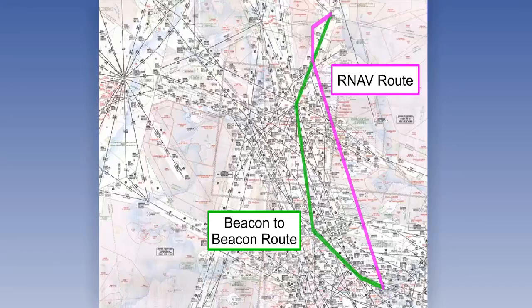An area navigation, or RNAV system, is a method of navigation which permits aircraft operations on any desired track within the coverage of station-referenced navigation signals, or within the limits of a self-contained navigation system, or a combination of these. This is the ICAO Annex 11 definition. So there is no requirement to fly directly over ground-based facilities.